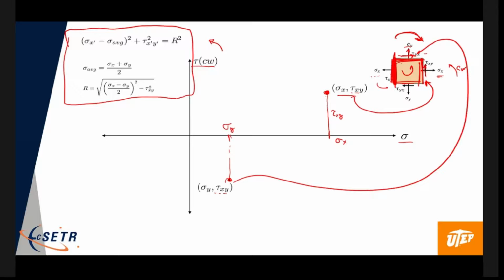So actually we get the same exact point. So this is also this face. And likewise, this point here is going to turn out to be identical to this bottom face. So for a given state of stress, we get 2 points. And that's what's shown here. Those 2 points correspond to the tractions, if you will, the stresses on the cube in that orientation.